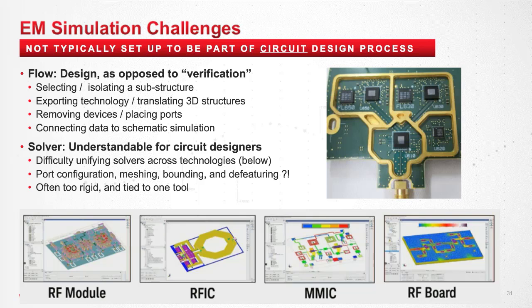What I'm saying is, as we move to wafer level packaging, that changes. That's not the case anymore. When you design the chip now, you've got to also design all of that package potentially out to the board. That's one of the things we're seeing internally: with these chips, if we want to get the performance, we have to go all the way out to the board at the higher frequencies. So there's all these pieces of the EM that are difficult.